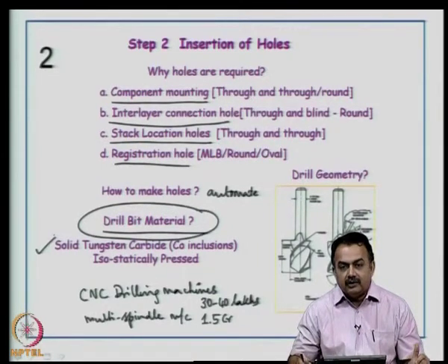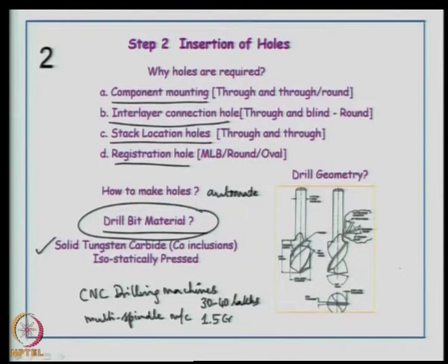I would like the figure to be shown here in this slide. You can see there are various formats of drill bits available, but for a CNC drilling machine on such a tough substrate, you will use a turbo shank, and you can see these sharp edges here. This is a tungsten carbide drill bit. So, there will be a lot of length available for this to be mounted, okay, and then you can resharpen it at least 1 or 2 times, so that you can reuse the material.